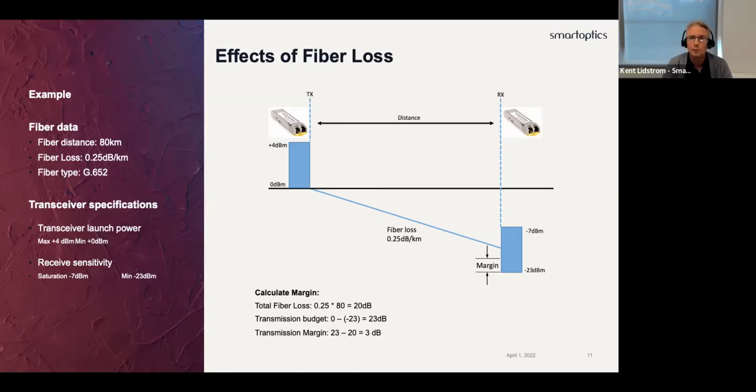So this is an example of how you do network design and calculate simple passive designs. If we were to put one of those multiplexers, a DWDM filter, in between here as well, they will also have an insertion loss that you need to take into consideration and calculate with. So depending on what kind of complexity you have on your network, there are a lot of parameters that you need to take into consideration when you design the network.